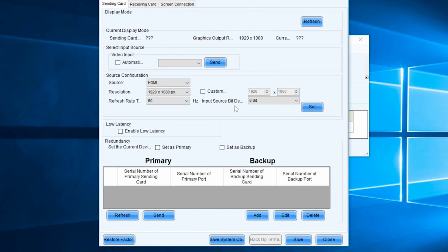So the media input, that's what this is coming up as. If this was incorrect, I would go through and on your sending box try and change the resolution, as opposed to changing the resolution on the Novastar itself, because then you'll have a mismatch of resolutions.